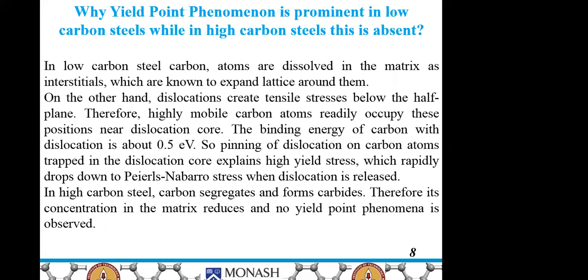Now, why is the yield point phenomenon prominent in low carbon steels, while in high carbon steels it is absent? So this is a very important question. In low carbon steels, atoms are dissolved in the matrix as interstitials, which are known to expand the lattice around them.